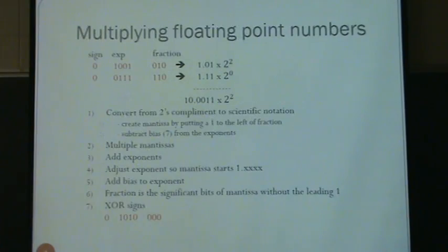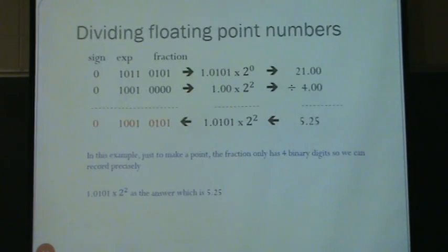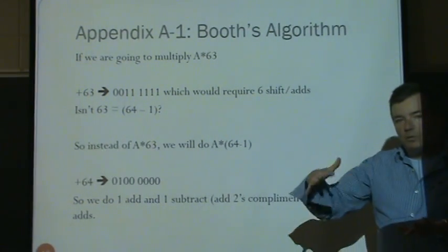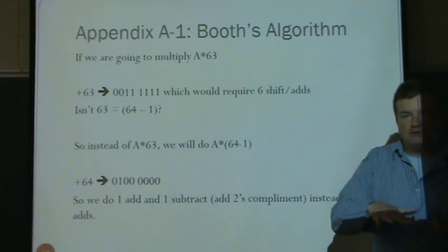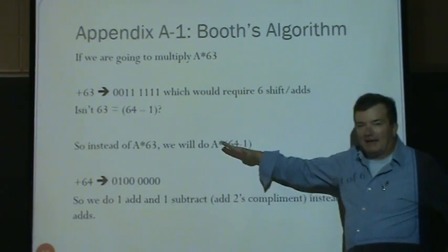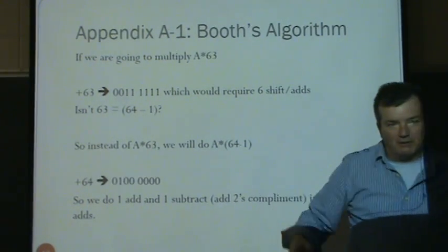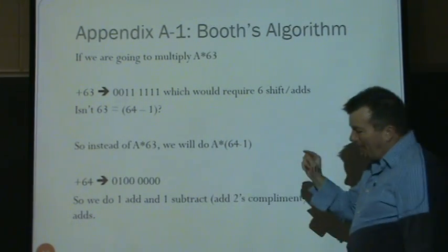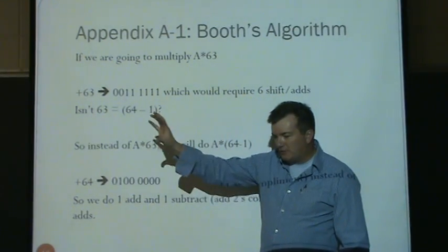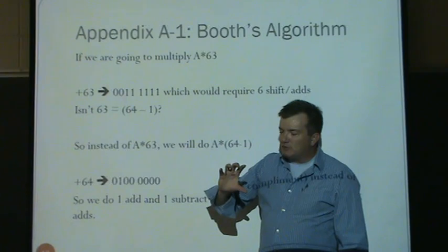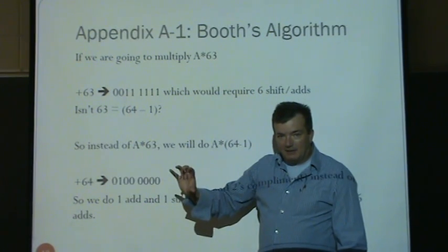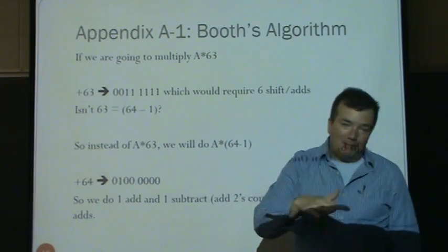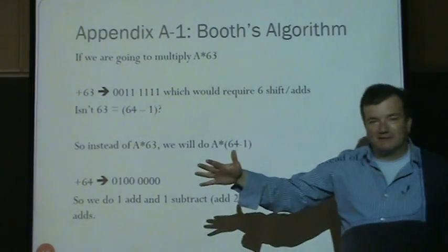So now the question is, if we're multiplying two 32-bit numbers together, what is the worst case? The most number of times we would have to add a number to itself, meaning we'll have another layer of hardware that's taking results from a previous layer. What would you say is the worst case? If you have a number A times a number B, and A is 32 bits and B is 32 bits, it's really the number of ones in B that will cause us to do an add. So in the worst case, there might be 32. If it's an unsigned number, they could all be ones.